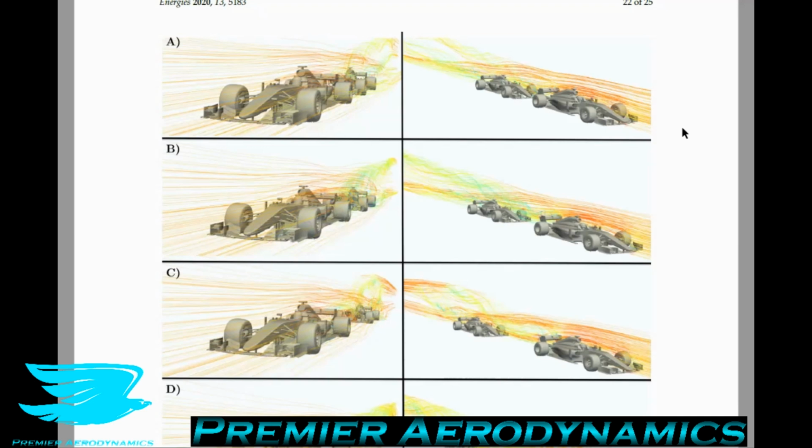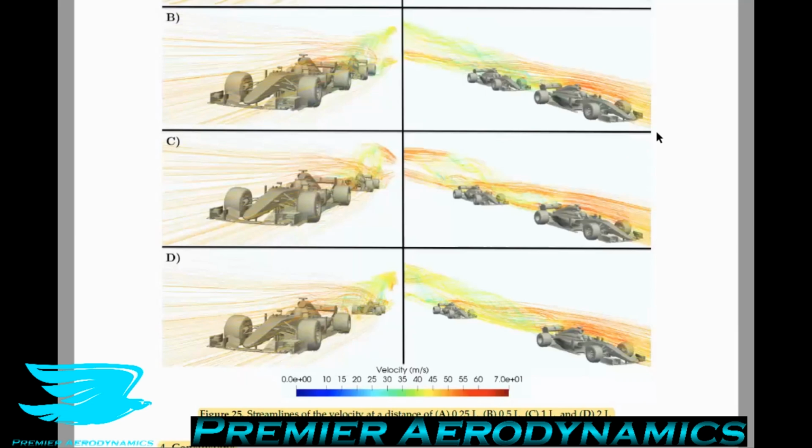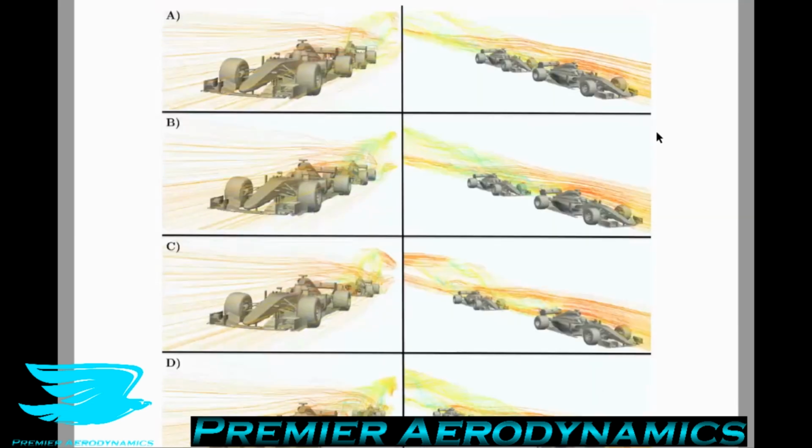But with these streamlines at an angle, the effective angle of attack might only drop to 20 degrees or 15 degrees or even less. So that means that this wing is now operating at a lower angle of attack range, which means that the lift or the downforce produced will naturally be lower. Not to mention that the rear wing will also not perform as expected because it's optimized for a 30-degree effective angle of attack, not a 15-degree effective angle of attack. So that's another reason why these flow control devices do suffer.